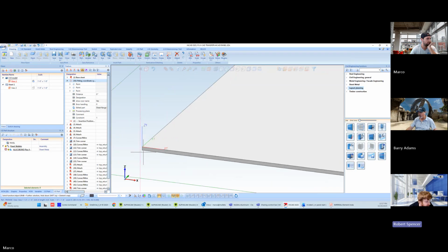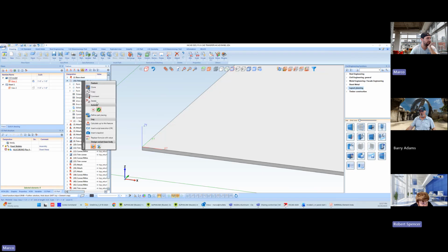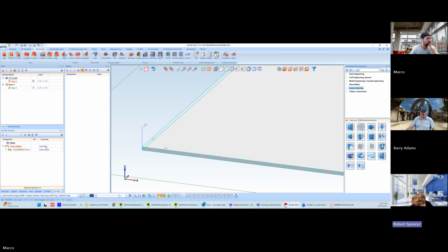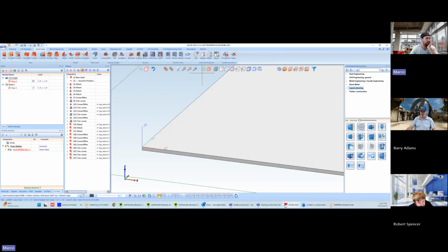Okay. So you see down there on edited part, a little bit further down in the feature step, you see that it's the sheet flange. You don't want to select the flange. You want the sheet to be the active part. So let's just delete this out. Sometimes you can clear out that instead, but sometimes it also doesn't work. So activate that and now call it up. Okay. We're gonna do plane, select.